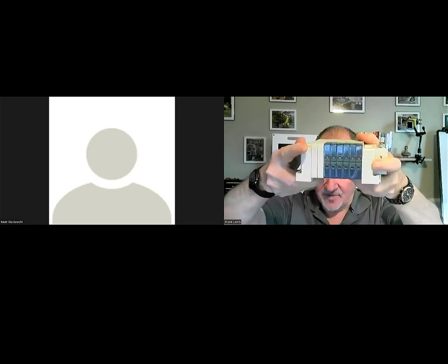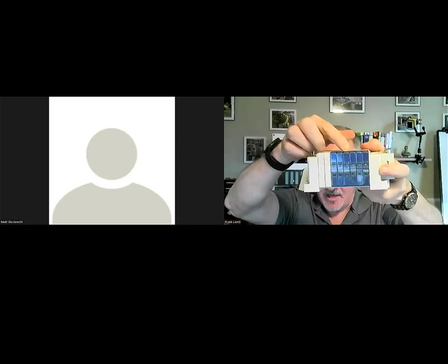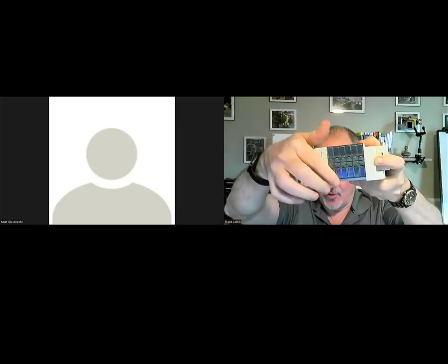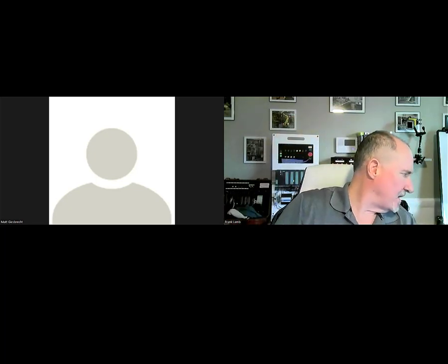And I've got blue hoses for extend and white hoses for retract on all those cylinders. So that made it a little bit easier to troubleshoot when I saw my hoses coming into one end or the other of the actuators. It was easier to follow things. And on the cylinder end, I also had labels on that particular machine. Here's a little better look at the solenoid valves themselves. You can see the extend and the retract, right? The A and the B ports of these valves. Let's see what else we got here in the toy box.